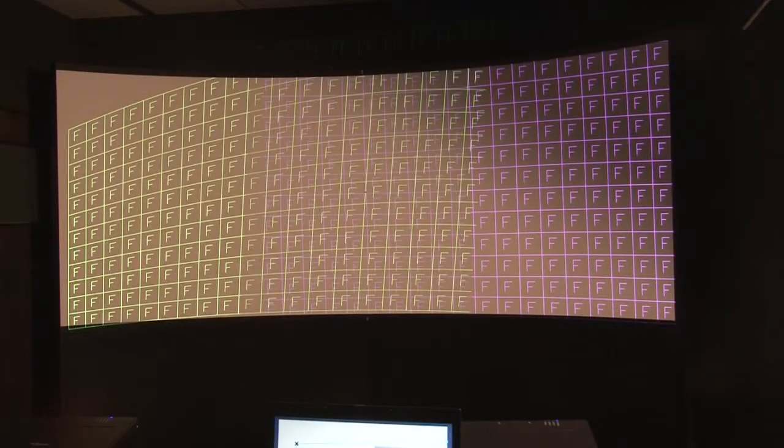So as you can now see, we've pre-configured the warp to the right hand scaler, the scaler driving the right hand VP793, so the picture is now square on the screen and nicely aligned with the border of the screen. It's just like one of those cookery programs where I've got one I prepared earlier. So now we're going to set up the left hand scaler, the left hand VP793 and projector, for which we're going to take you back to the view of the laptop.